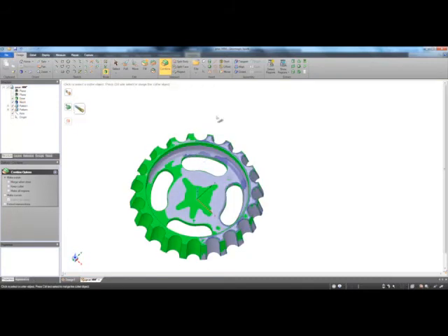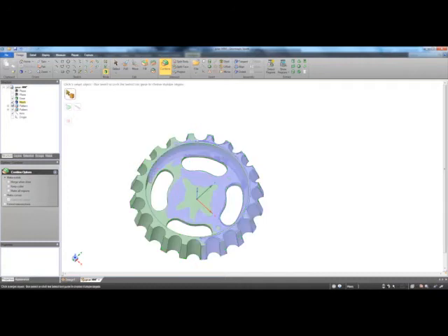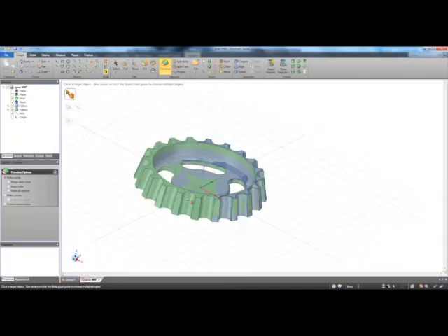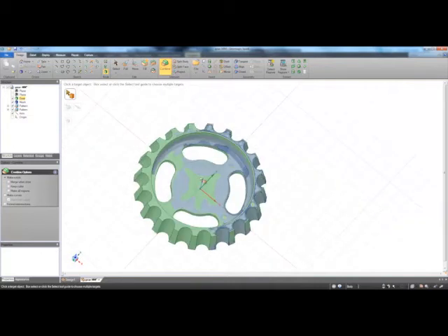And so now I essentially have everything done except for this inside part, which I'll now show the ability to do some sketching. So let me go ahead and choose the sketch mode on the left hand side. Up top you'll see an ability to do sketch mode. I'll choose that, and then now I need to choose where I want to sketch. So depending on which surface I select, that's where my sketch plane will show up.